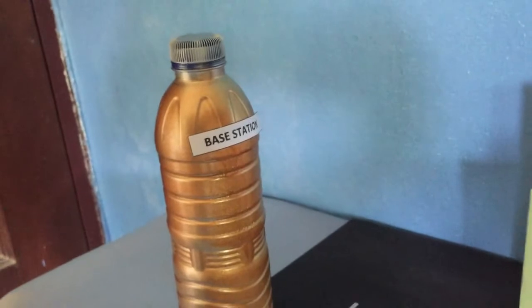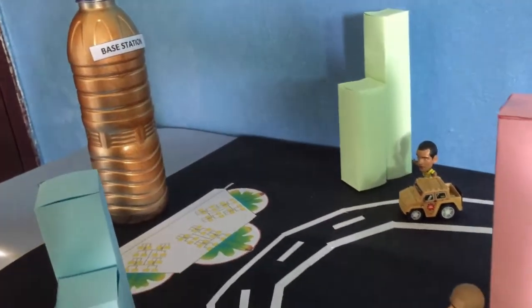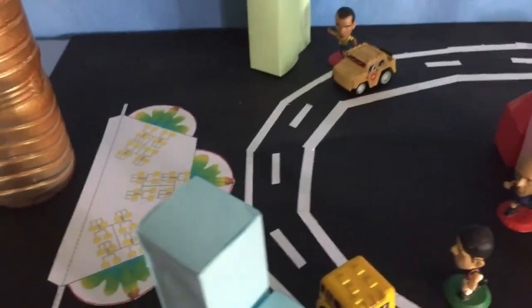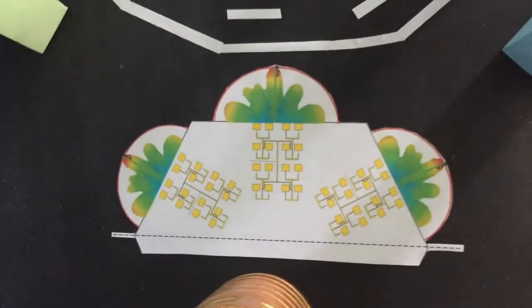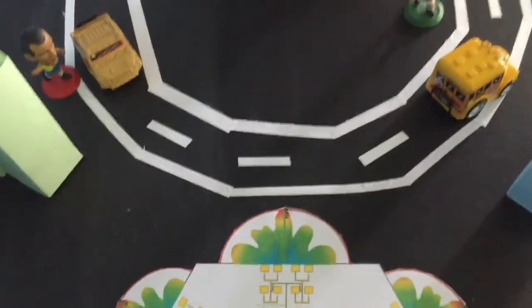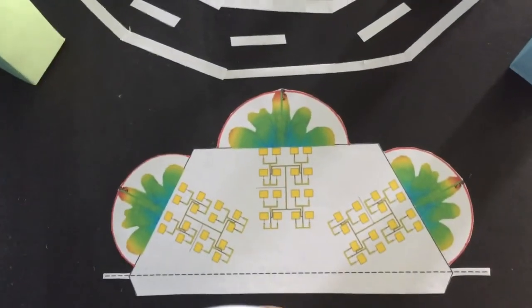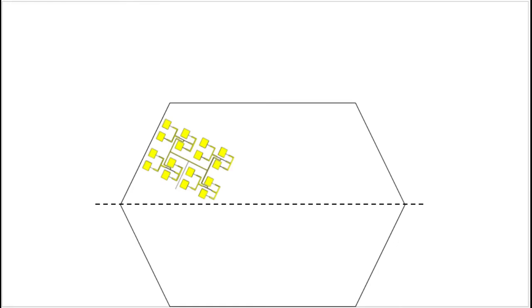This tower represents the base station, which locates the 4 times 4 array antenna that will be arranged in a semi-hexagonal shape. The reason for implementing this shape of design is that the semi-hexagonal shape is able to cover a wider coverage of 180 degree while remaining high gain, as the focus point of the radiation pattern for each array antenna is small.